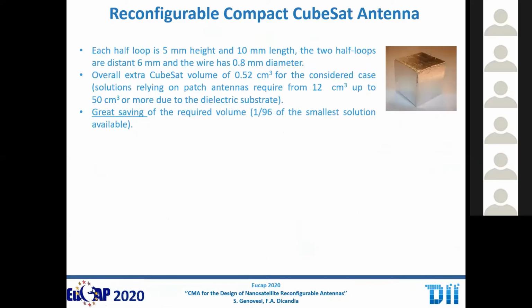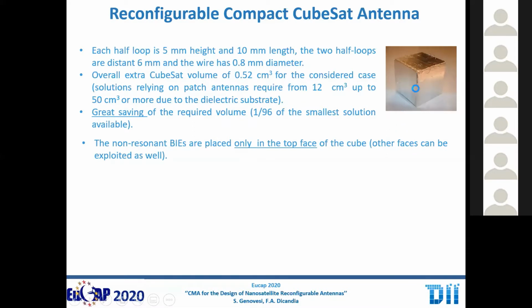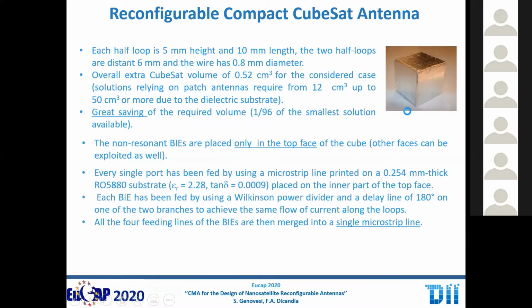Then, of course, we realized this homemade CubeSat mockup, and I want to stress that due to the employment of these exciters, we have a great saving of the required volume compared again to the solution with patch antennas. And also a lighter solution, because patch antennas, of course, require the dielectric substrate. And again, we decided to exploit only the top face, but of course we can use also other faces as well. And then, of course, you need some feeding line beneath this top face, and everything so boils down to